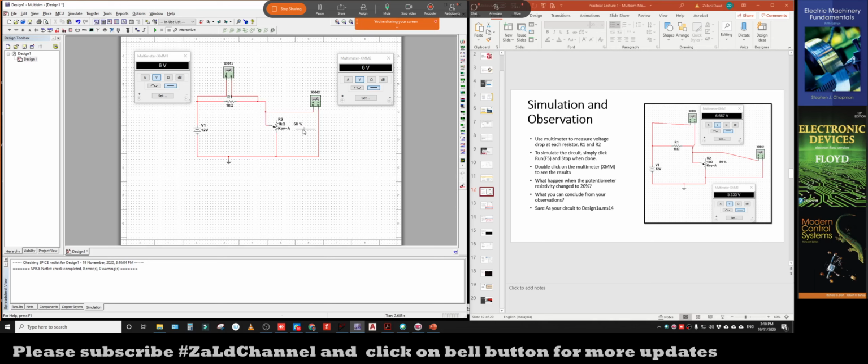So that sort of thing, you can use this dialer to adjust or change the sensitivity of this resistor, which functions like the dialer that I've shown to you for this potentiometer. We have the dialer here. We can rotate this to adjust the resistivity of the resistor, for example in some application where we would like to change the sensitivity of the sensors, or we want to adjust the amplification when we use this for an amplifier. We want to make the output of the voltage bigger or smaller. We can adjust this.